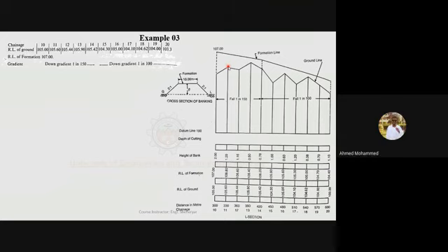I think the same one which you calculate in the beginning. We'll take the average of the beginning of the line and the end of the line. No. If I ask you what will be the height of filling at this point, that was for the whole road segment. I'm just asking about each individual point. Let's say I'm taking measurements at this point. So what will be the height of filling